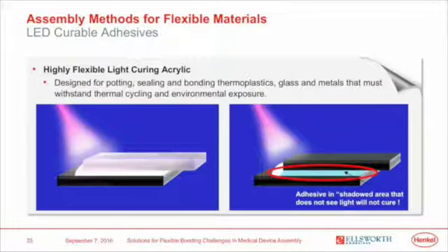But on the right side, when you have that black or opaque component, this is a chemistry that does require full exposure to light. So even though you have high-powered LEDs, if one of the components is completely light blocking, the adhesive in the shadow areas will not cure. The cure does not propagate. Just something to keep in mind: this particular solution for flexible materials does require full exposure to light.